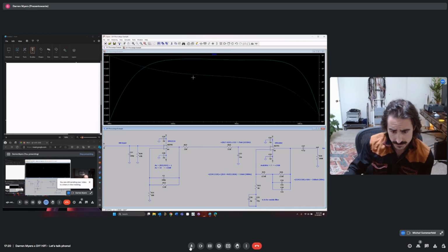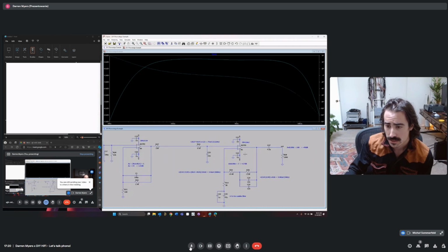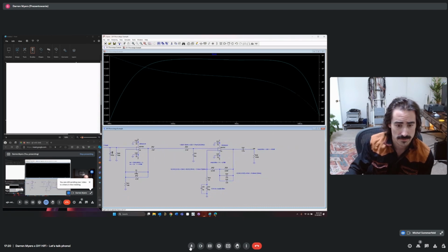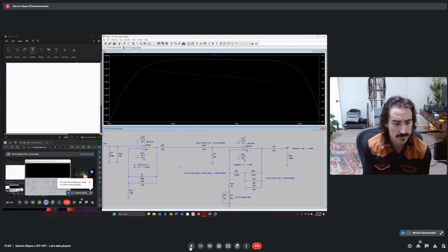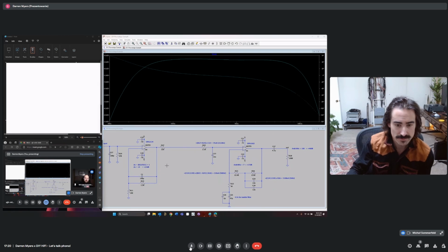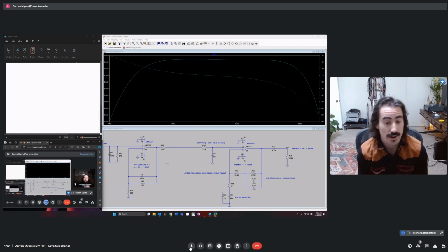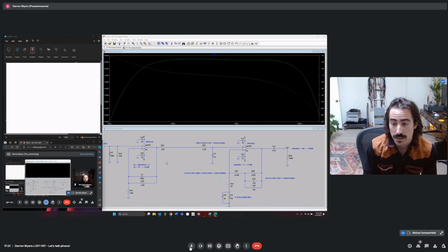Okay. One quick question, because we all know that DIYers love to roll op-amps. Besides all the variants of OPAs and JRCs and Muses and everything else, which is quite obvious, just match the parameters. How do you feel about using discrete op-amps in here, like the things that Sparkos does, or other companies, or Burson? I think it's great. Yeah, and those designs would be stable in this topology.